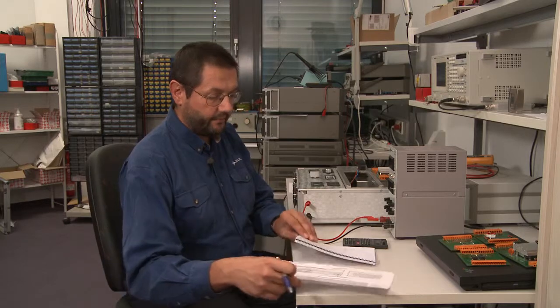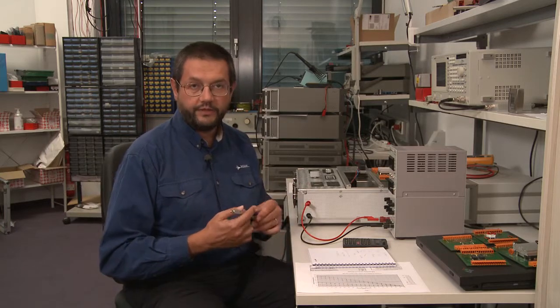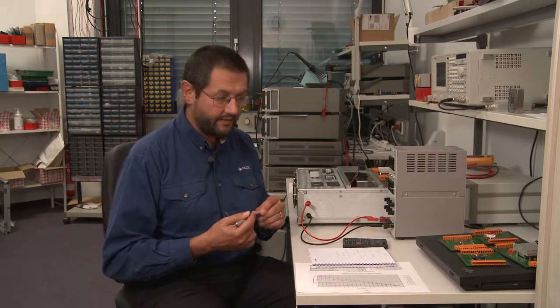And with this, we can also see that these curves are a little bit conservative, which is good for a good design, because we saw that by running the module at 50 watt output power, we had an increase of temperature up to 80 degrees C, which gave us a 20 degrees C margin before reaching the 100 degrees C limit.